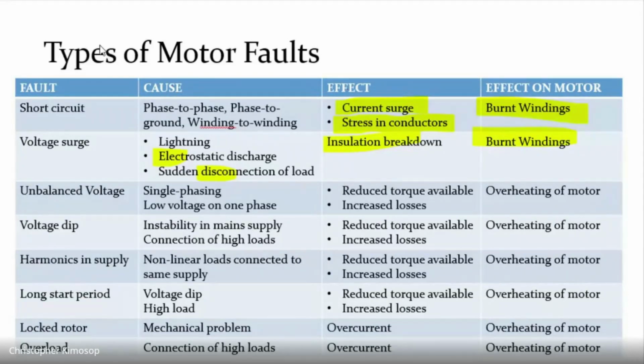What might happen is, if you have 3 phases, it can be even something as Kenya Power, the supply outside there, your 3-phase supply, one of the conductors breaks, one of the wires that are outside your own premises, and Kenya Power's supply is only supplying, say, red phase and yellow phase, or yellow phase and blue phase, whatever it is. This is a situation we call single phasing.